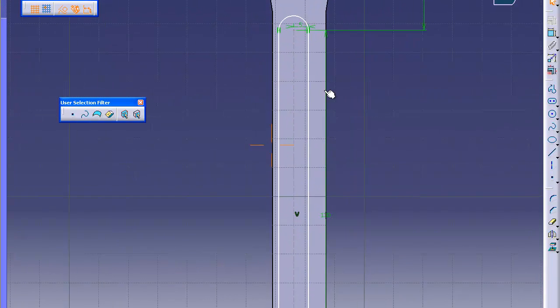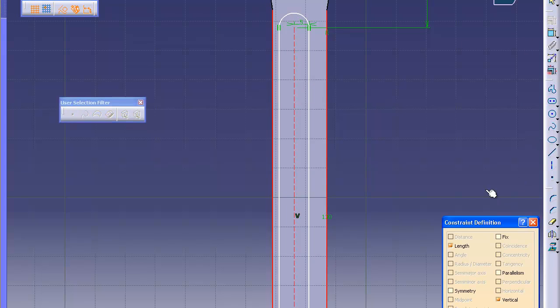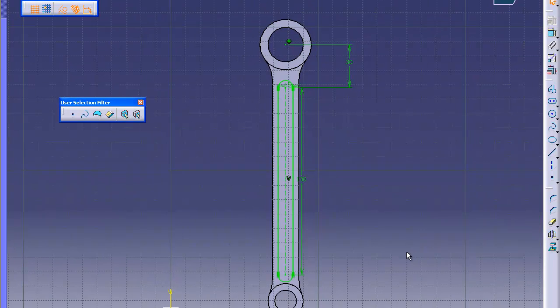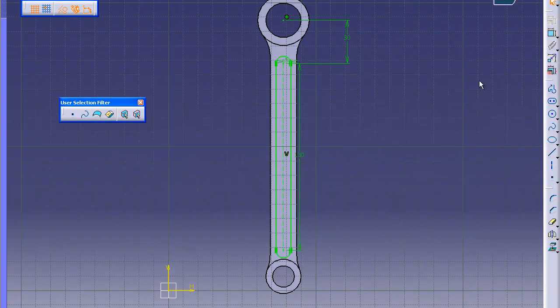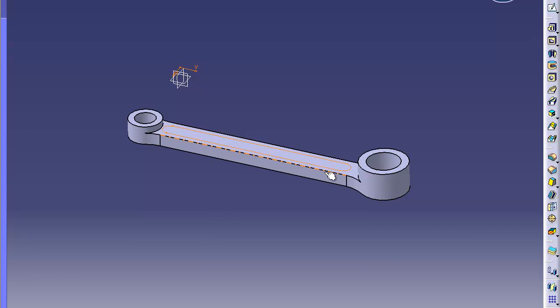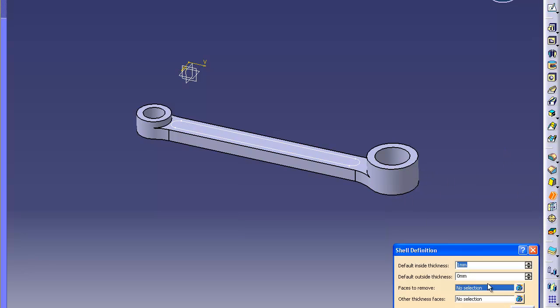And lastly, we just use each edge of the solid model and the central axis of the elongated hole to make it symmetric and centered. There you go. Sketcher's green and we're good to go. So exit Sketcher. There's our sketch. The last thing we have to do is just pocket this to a depth of 6.5 millimeters.